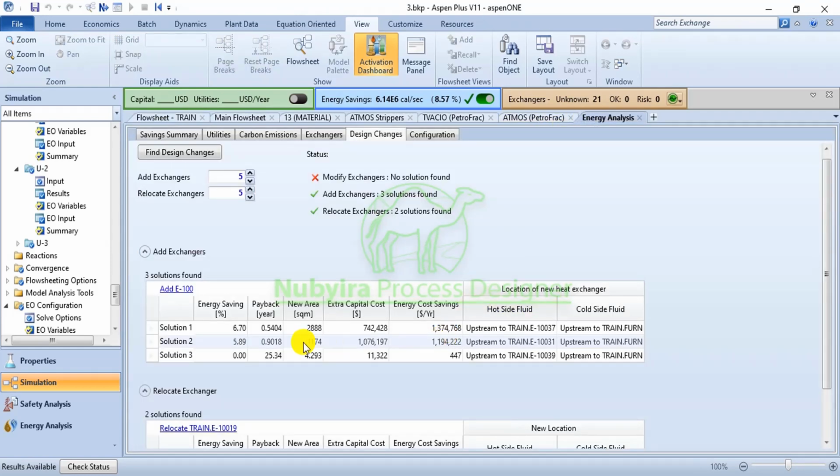So what you should consider in all this is the extra capital cost. If it is minimal compared to others, then you can see this will increase the capital cost of the solution. Engineering is just about balance and making sacrifices, compromising. You understand? You can't get the right thing, but you should know what to sacrifice for others. You want to increase the efficiency, the integration. The process of burning a lot of fuel is not an efficient way. But you can just incur extra capital cost for the new heat exchanger to design, for the retrofit design.